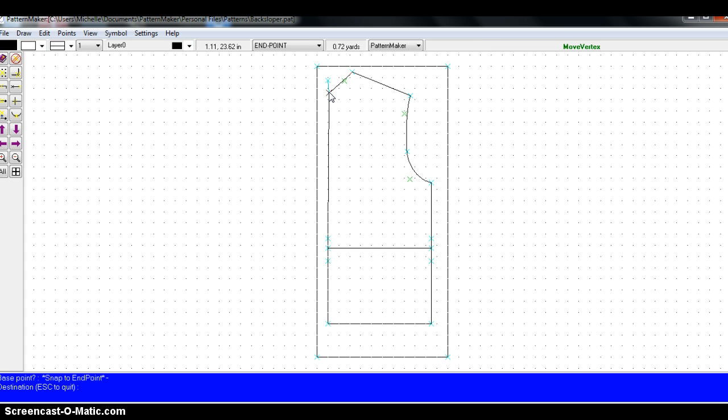Now, to put this point on the grid point, select Snap to Grid. That's going to be Control F2 for our function. And that way it snaps to the grid points. If the grid was not already on, it would automatically come on screen as well.